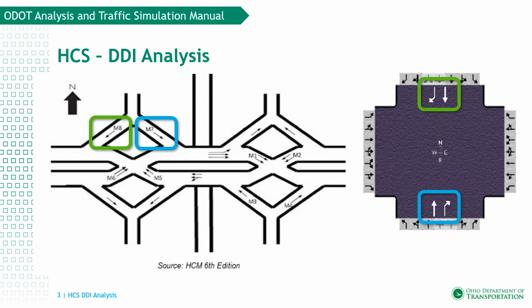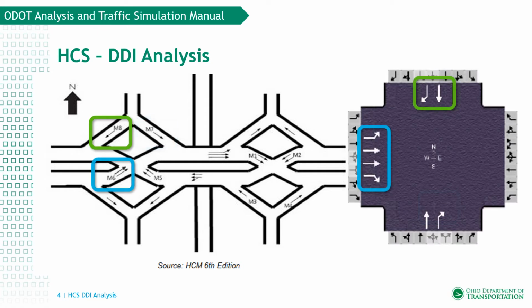As with the southbound approach, a northbound through lane is also added with a volume of 1 to accommodate the HCM requirements that approach has a through lane. In order to create an overlap phase between the southbound right turn movement from the off-ramp and the eastbound through movement at the crossover intersection, an exclusive left turn lane should be added in the eastbound direction. This left turn should have a demand volume of 1 vehicle.